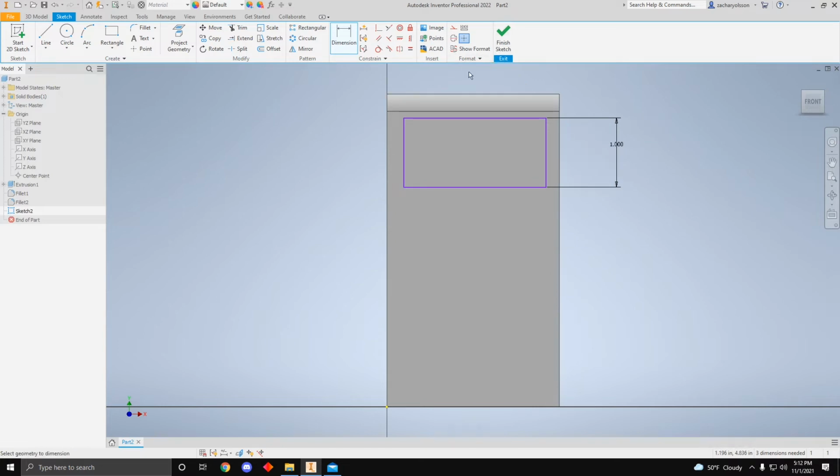And that's really all the size we need. The other thing you can do is, instead of dimensioning the size of this, you can grab the dimension of this and the edge of this extrusion, and you can bring it over here. And let's say we want to make this 0.1. It'll actually make this bigger because it's wanting to be 0.1 away.